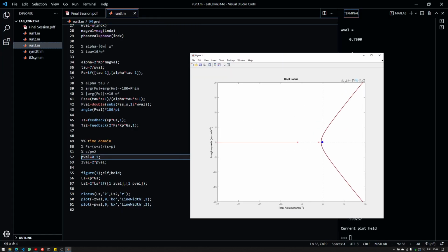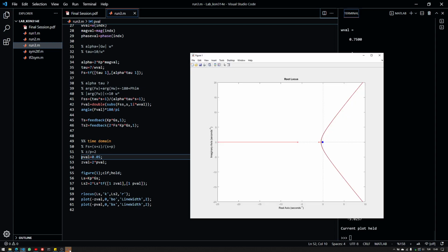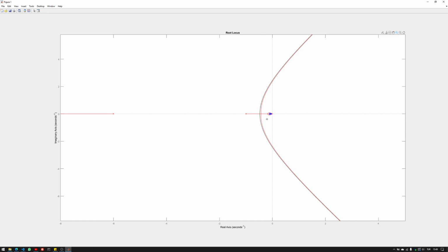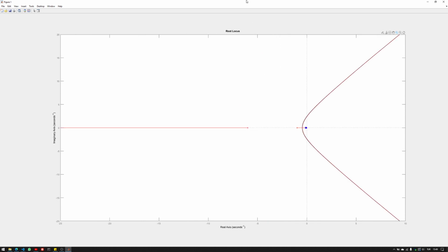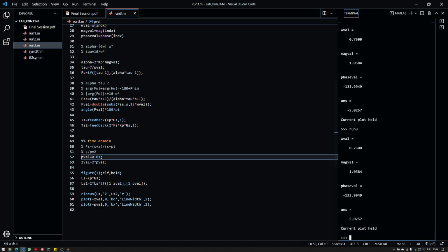I can still see some potential here. Maybe I should use an even smaller p val, so closer to the origin. The pair should be closer to the origin. Now you can see that the closer I get to the origin, the better the approximation of the updated root locus looks. It will still have an effect, I can't prevent that, but I want to match these branches as much as I can. So this one hopefully should work as expected. Now let's use an even smaller p.